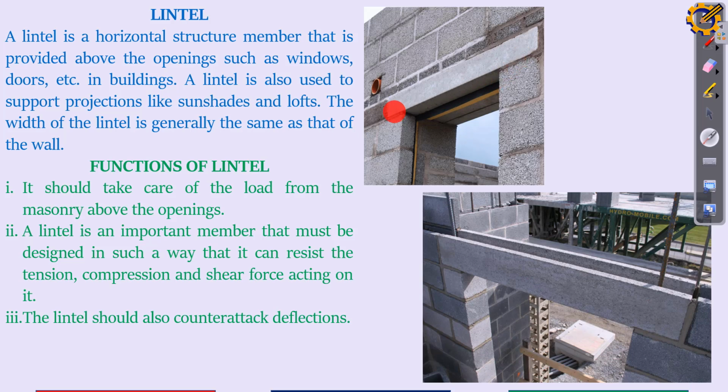A lintel. So a lintel is actually placed above a wall opening. When we talk about wall openings, we talk about the areas where your windows and doors are located. That's where you actually need a lintel, because if there's no lintel here, and maybe you just pour concrete without reinforcement, or you start laying blocks on top, everything will fall on your head.